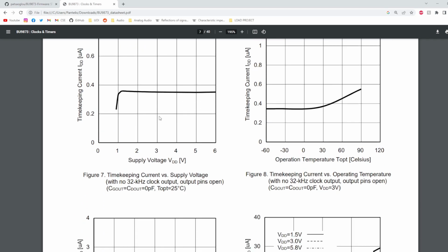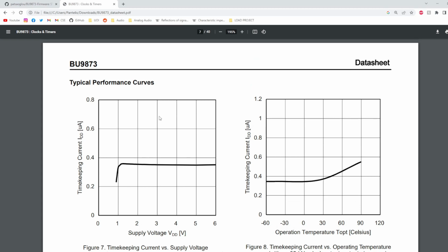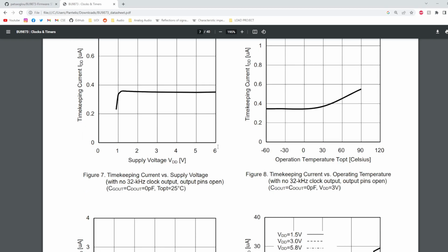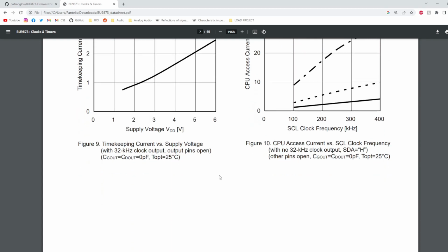These are important when you want to select a component that has the performance that you might look for, and you basically check those in peripherals that have ADCs and DACs, where you care more about the noise performance, the frequency response and the frequency performance of the IC.